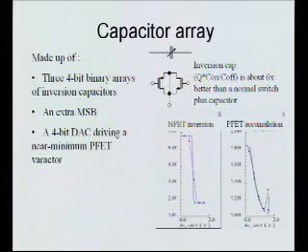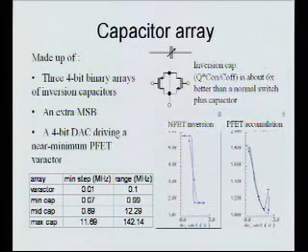So then the only problem is that your LSB, the smallest thing you can get, is the smallest transistor you can get, and that's maybe not a small enough capacitive step. So to tack on a few more bits worth of accuracy, I used a single 4-bit DAC driving a single true varactor that's just variable, and that picked up my last few, literally attofarads of capacitance variation, like tens of attofarads. That's tiny, really hard.